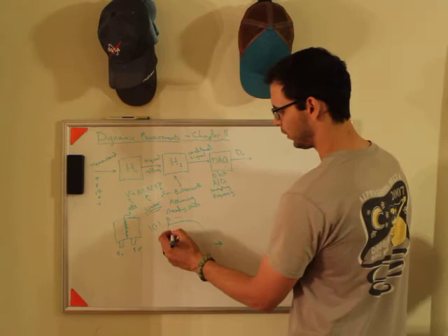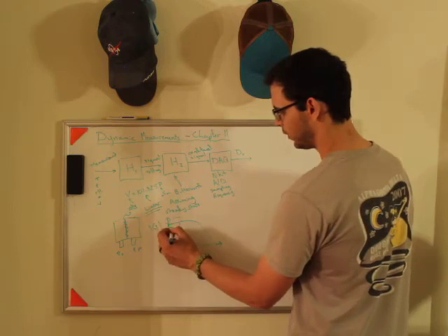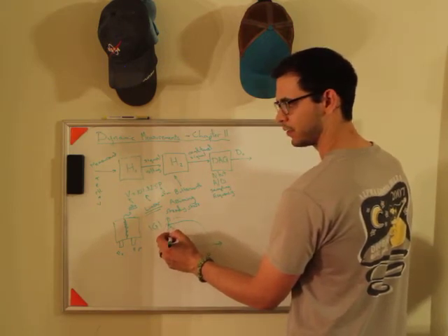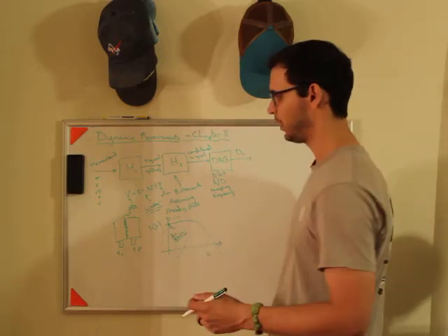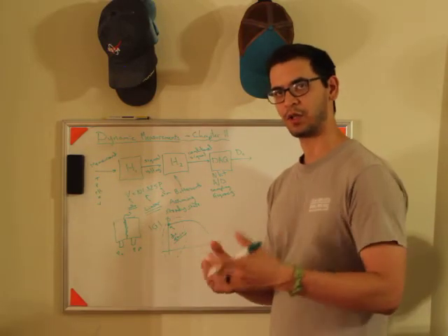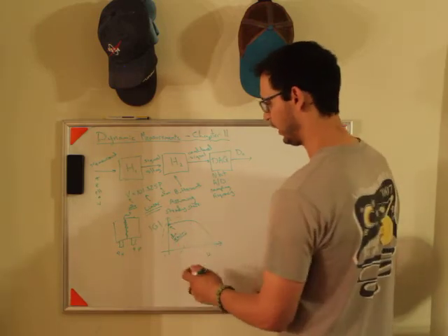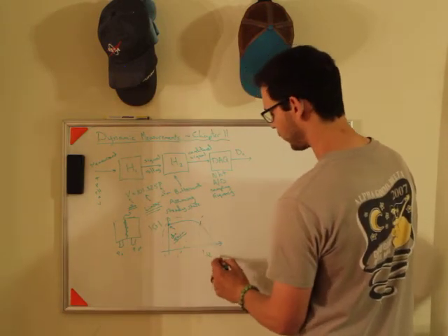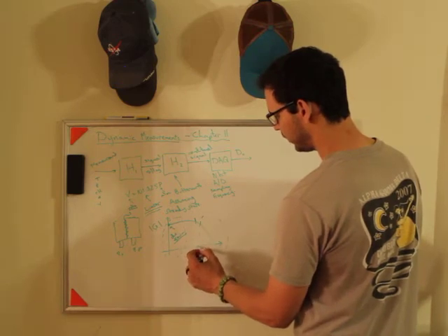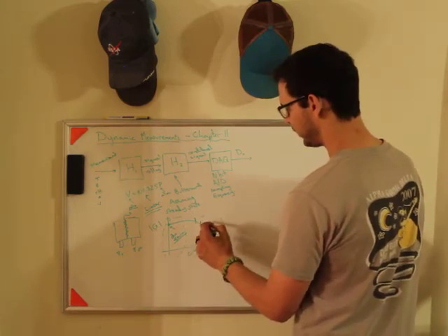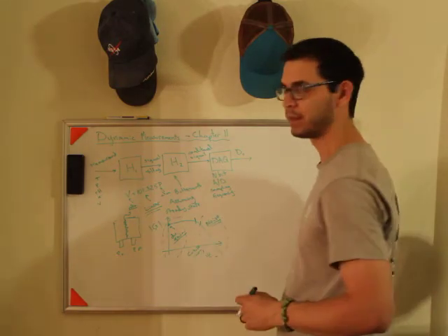And so we were assuming, this is sort of your, what is this thing called? It's called your DC gain. And it makes sense because it's basically saying this is like a direct current gain that you're looking at. Everything over here, the reason why we have it roll off at some cutoff frequency is because we assume that this out here is noise.